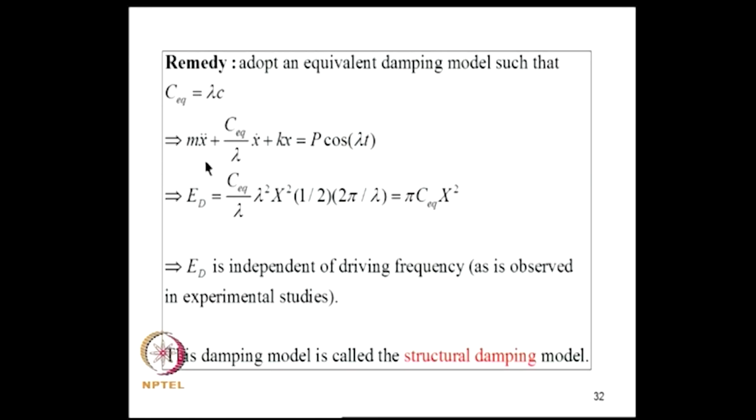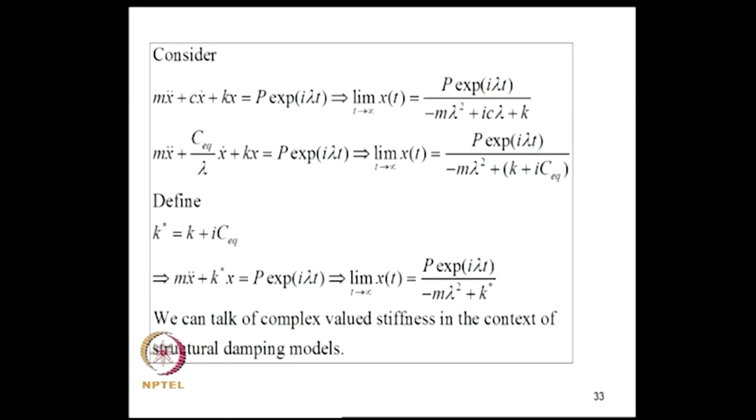Now, you have to pay attention to this equation: this lambda is the same as this lambda. So, this is not a differential equation in the traditional sense. For example, there is nothing like free vibration here. When you put the right hand side as 0, what lambda do you put here? That is not defined. So, it is defined only when there is a harmonic excitation, and this model works only in steady state. So, you have to bear that in mind.